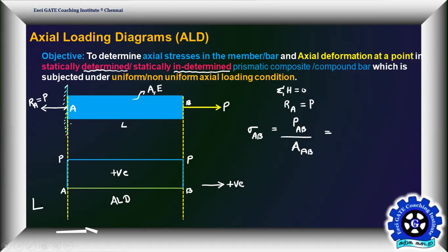You will see the load here and length here. Load versus length diagram. Load you will see on the y-axis, length on the x-axis. What is the load acting in the entire portion? P, right? Yes, sir. By area of cross section A. Area of cross section A is nothing but pi d square by 4, so 4P by pi d square. You will get it. Correct?